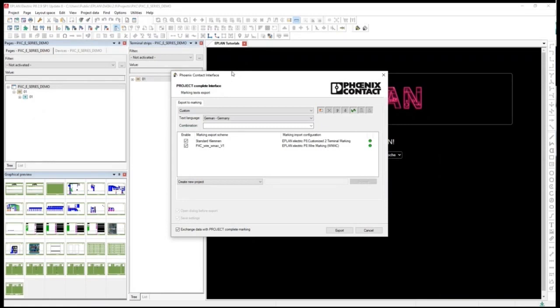If you want to import this back to Eplan, then the only thing you have to use is planning, because in planning you see which level is also marked, and you have two possibilities. For terminal blocks with more levels, I recommend using planning, because planning really checks on which level the marking information is.